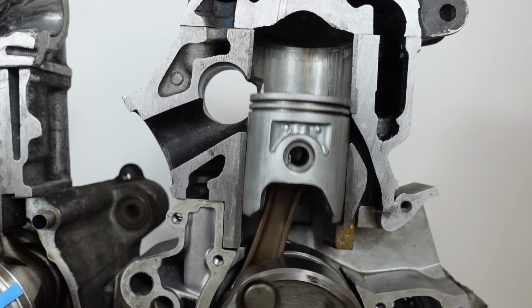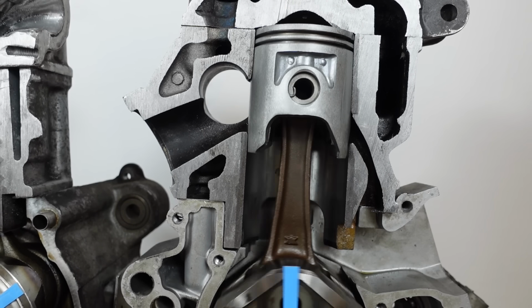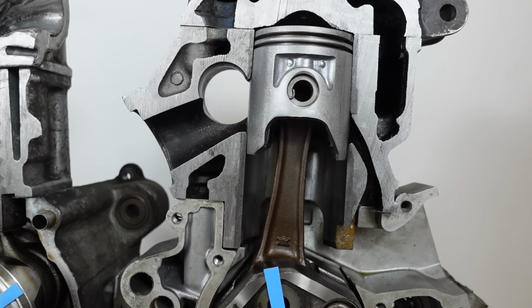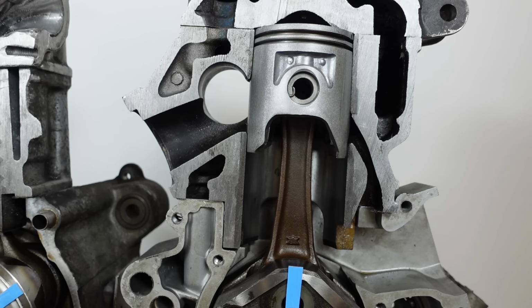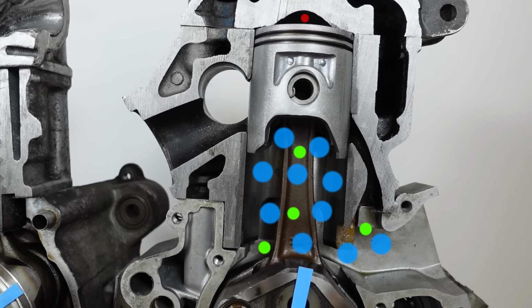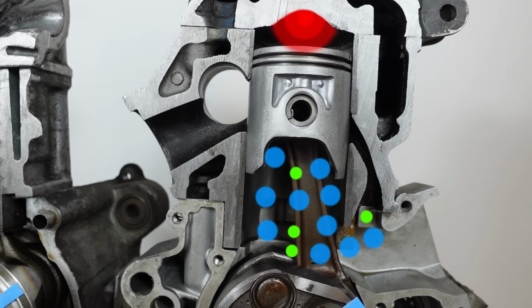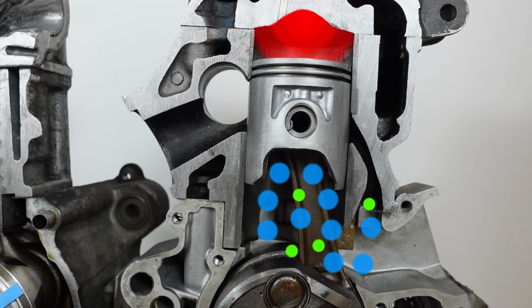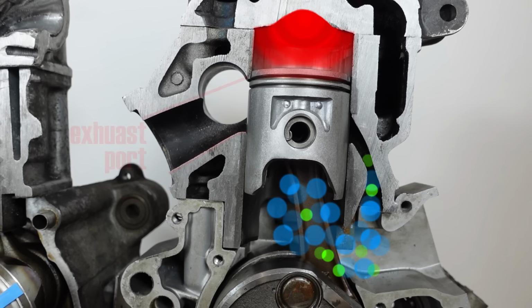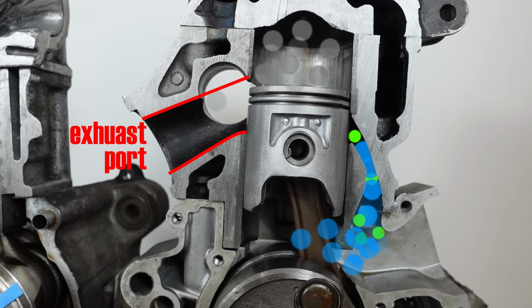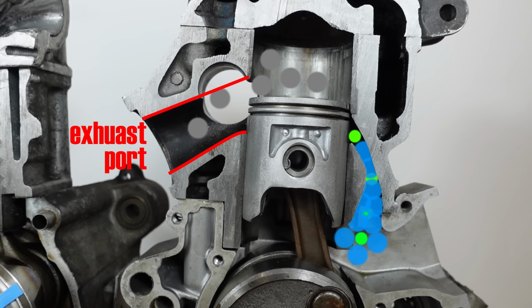Now let's observe the combustion cycle in a two-stroke, and we're starting with the combustion stroke itself and the piston at top dead center. So combustion has just started, it's building pressure in the cylinder and pushing the piston down, while at the same time we have fresh air-fuel mixture below the piston, and I'll explain how it got there in just a moment. Now as the piston is going down, it opens up the exhaust port, which allows some of the exhaust gas to start escaping from the cylinder.